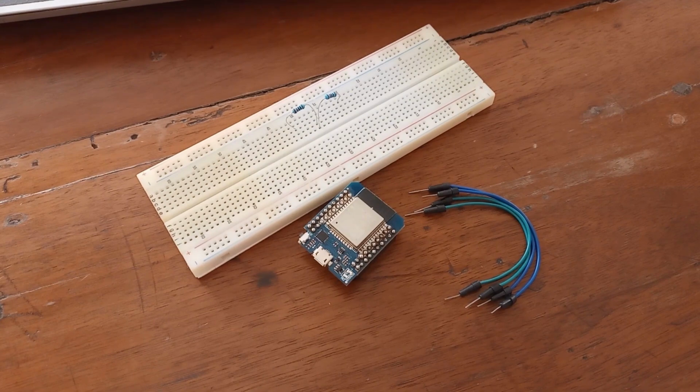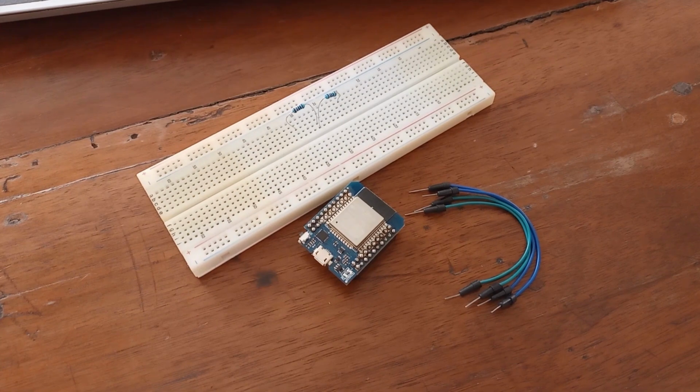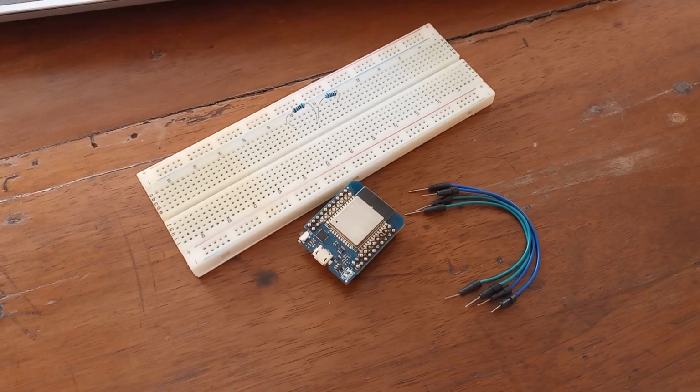Well, in deep sleep mode, your microcontroller consumes between 10 and 150 microamps, which is excellent for this purpose. And finally, how to implement this solution. You are going to throw your microcontroller in deep sleep mode whenever it doesn't need to be active. For example, you have some sensor attached to it that is going to be used from time to time. You want to be able to activate it whenever you need it. But in the rest of time, you need to preserve your battery.